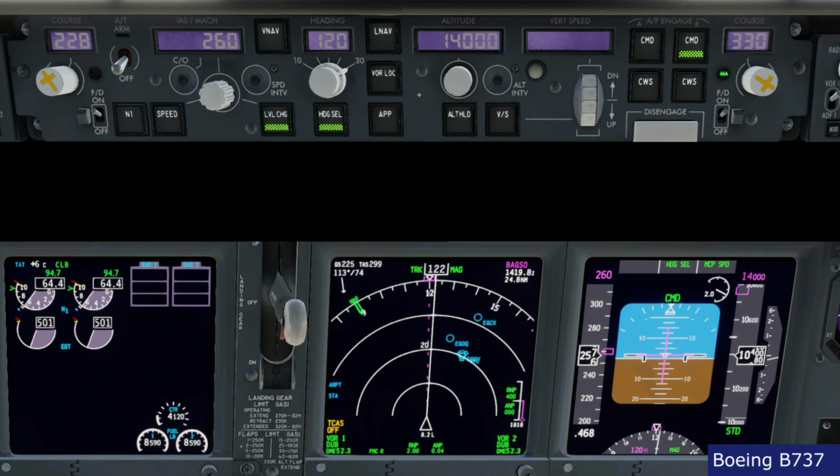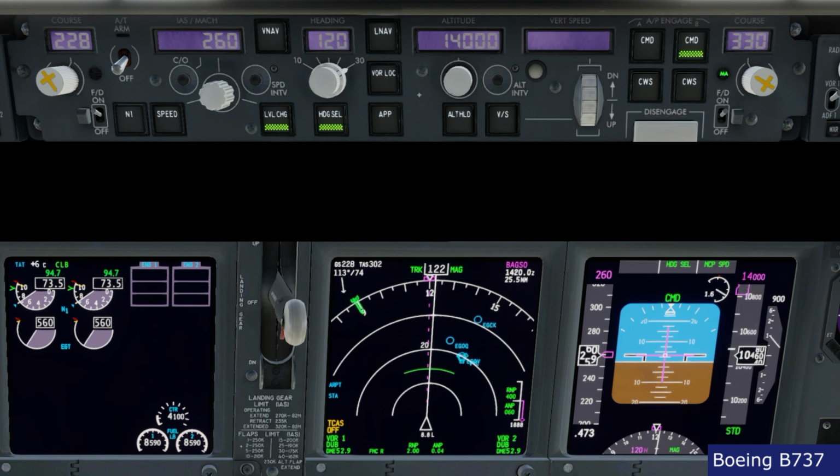So sometimes it happens that in level flight, manual flight with flight director, I ask the pilot to make a climb and the pilot forgets to give thrust, or gives just a little bit of thrust, as I'm doing now, around 72%, which is a bit more than what you need for level flight, in the range of 55-60%. And you see what happened, we got a very small climb and the pilot wonders why we're not climbing, and eventually I ask why we're not climbing and the pilot can't find an answer. Well, the answer is very simple: you didn't select thrust.